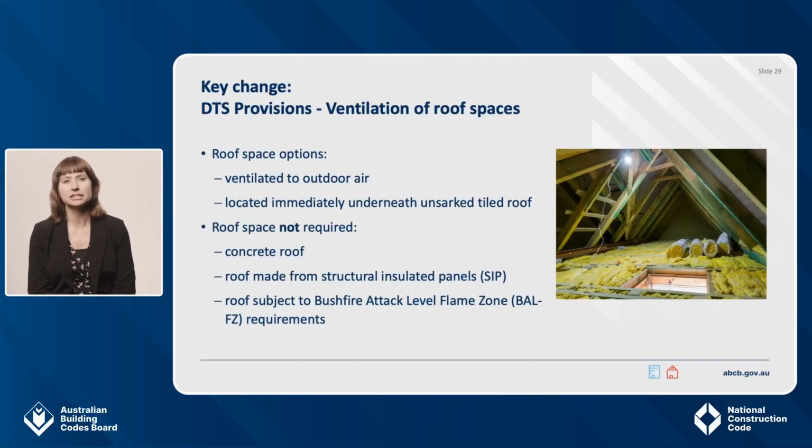Secondly, the roof space needs to be ventilated to outdoor air through evenly distributed openings. The ventilation opening details depend upon the roof pitch and the type of roof. The ventilation openings are not required for a roof space which is located immediately underneath an unsarked tiled roof. There are exemptions which apply to a concrete roof, a roof made from structural insulated panels, and a roof subject to BAL FZ requirements, which are the most onerous level of requirements for buildings located in a bushfire-prone area.